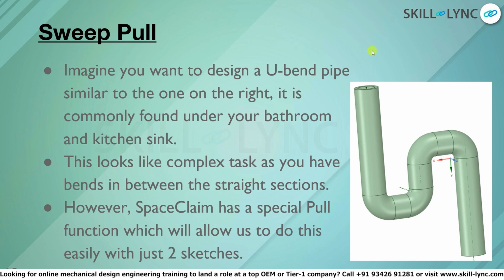So how would we go about designing such a pipe? It looks like quite a complex task, as you have curves and sweeps in between the straight sections. So even if you were to design all of these straight portions of the pipe, how would you go about designing this curved portion of the pipe? You could do a bit of a revolve around an axis over here in this corner, then another revolve, pull around an axis in this corner.